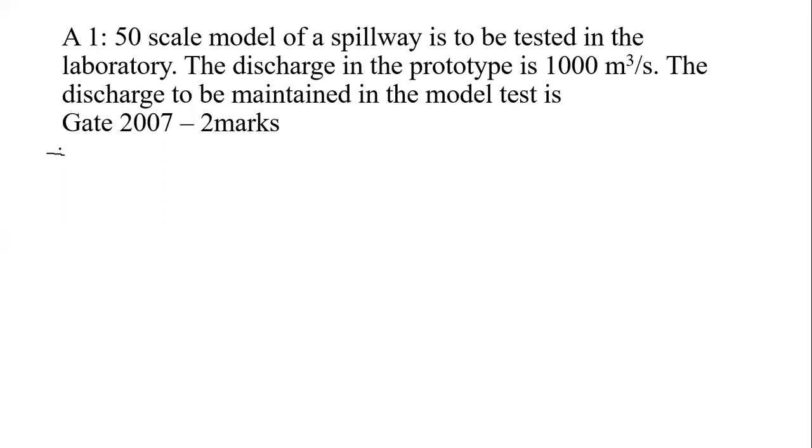LR, the length scale ratio, is equal to length of model divided by length of proto, equal to 1 by 50. It means that if the length of proto is 50 meters, then the length of model will be 1 meter.